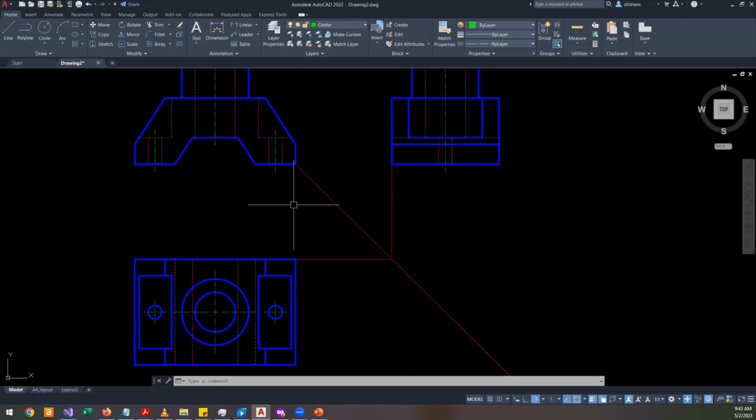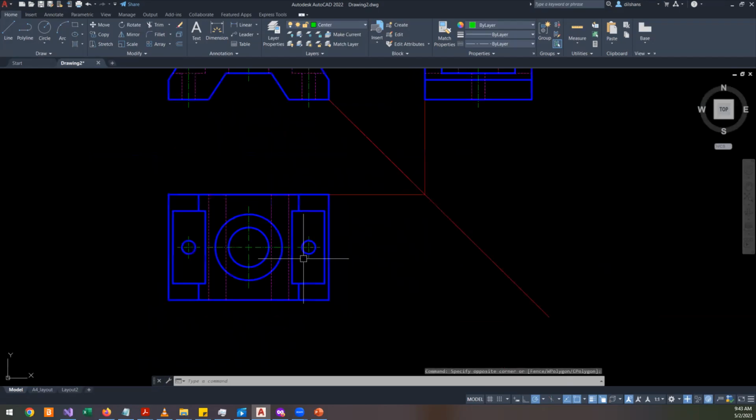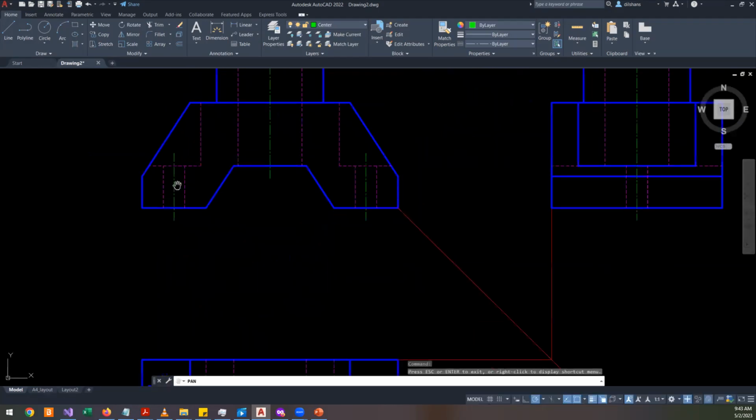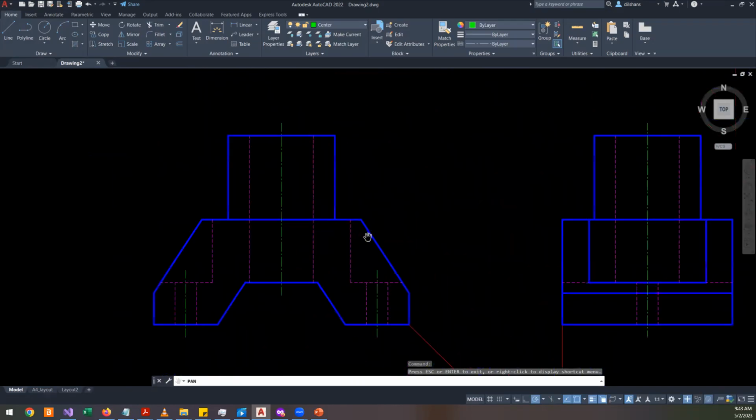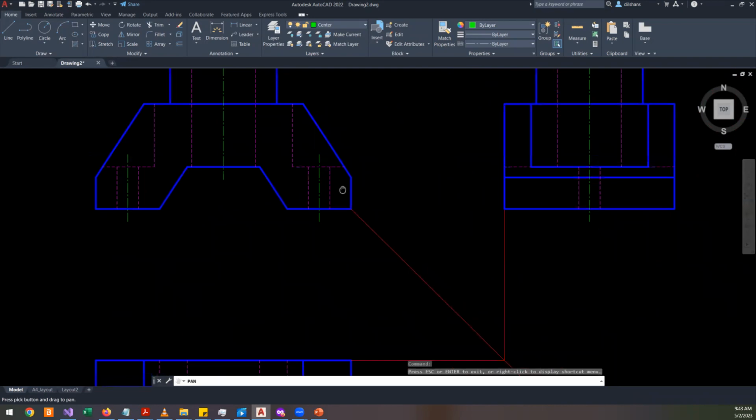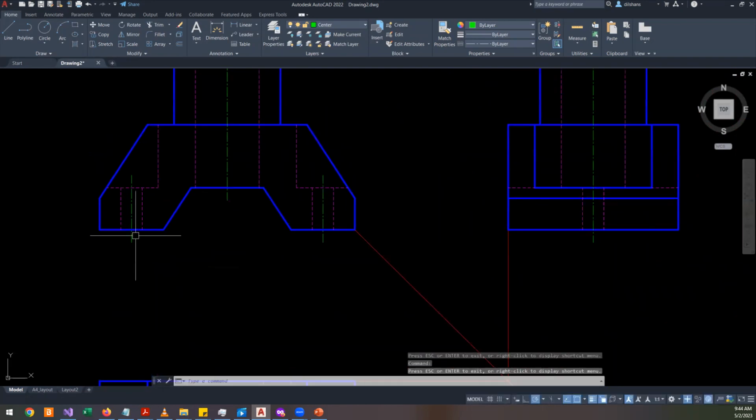So you need to include view labels like front elevation, end elevation, plan, add dimensions into your drawing, and draw the center marks like this. After this, it should be almost a complete drawing. But still, you need to know about plotting so that you can produce the output. Once you get to this point, you have almost completed the 2D drawing part. I can safely say that.